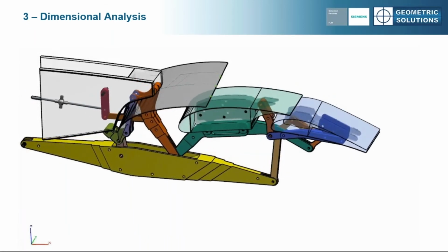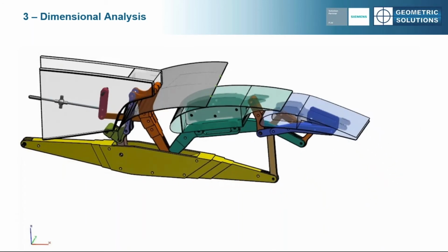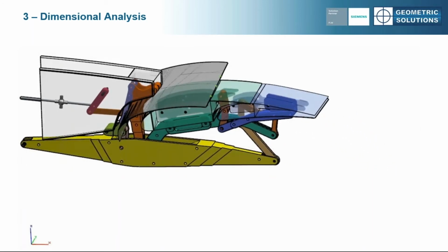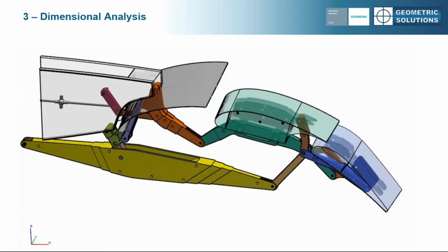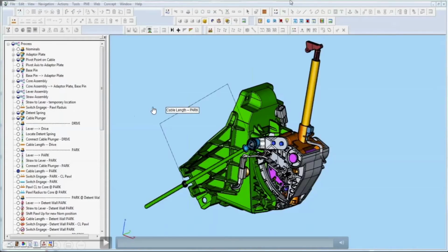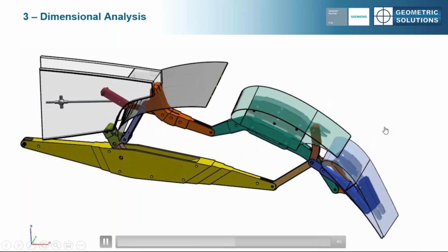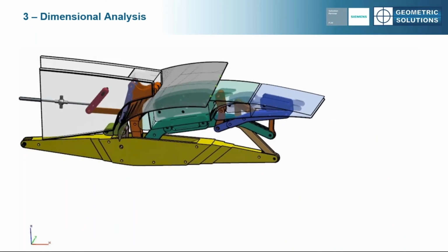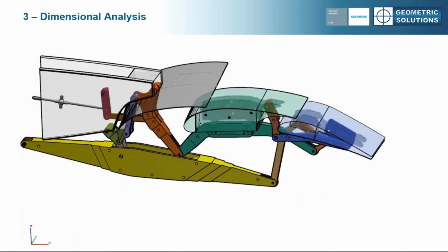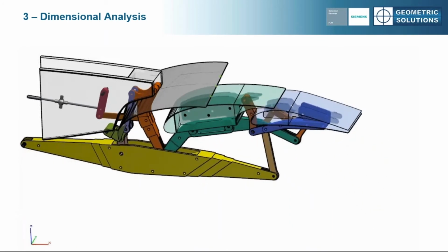Here's another reason we do it up front. This was a slice through a wing, and these are the dual flaps at the back end. The goal was the trailing edge of that wing, this trailing edge back here, they wanted to hold it at plus or minus 30 thousandths when fully deployed. The results of this model was like plus or minus 380 thousandths, 12 times as much. It was way out of spec.